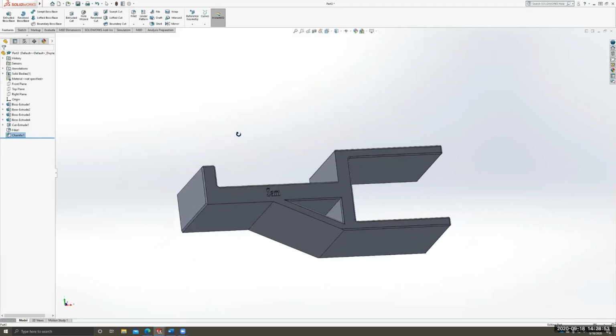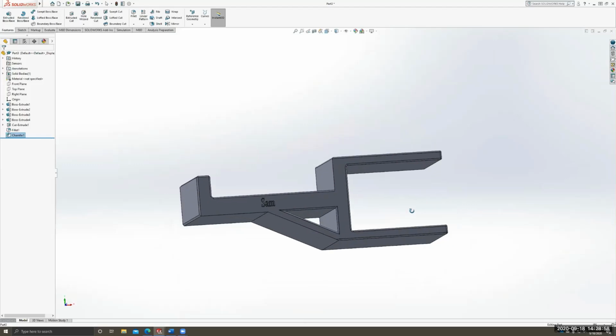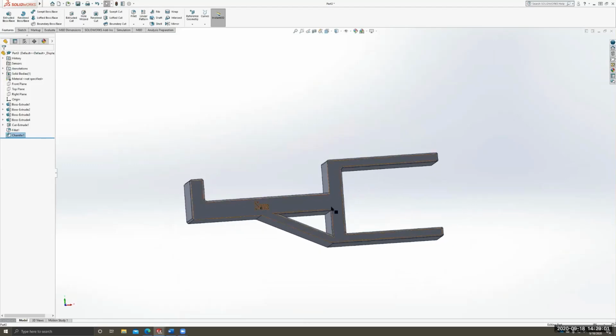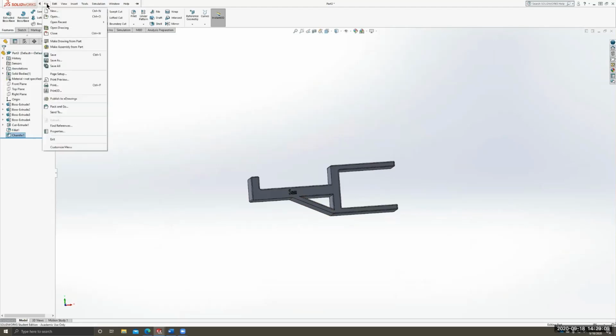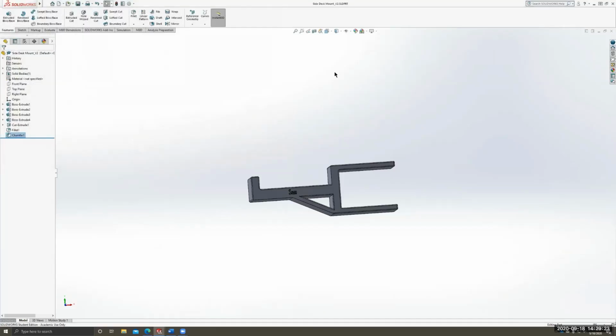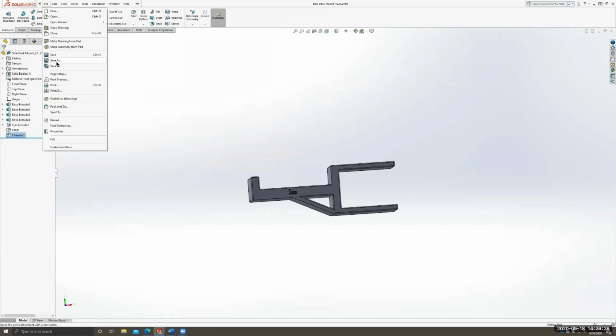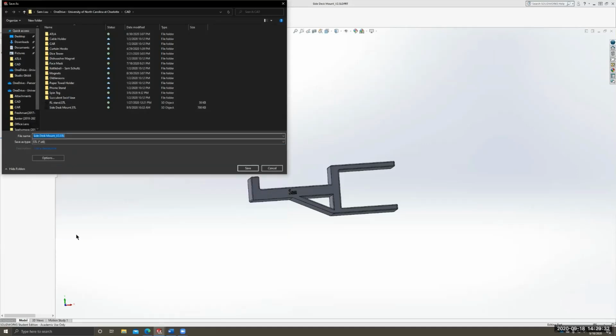So this is basically the headphone holder. I'm going to 3D print mine, and hopefully it'll work better this time. And you guys can submit yours to 3D print. I can show you guys how to save it as an STL, which is what we use for 3D printing. So we can save ours as, I'll do side desk mount version 2. I save that as the SolidWorks part, and then to save it as an STL, you go to Save As, and then you just have to scroll all the way down to STL.